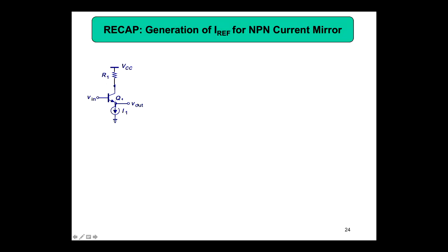It is an emitter follower, because here your input is to the base and the output is from the emitter. And then here you need an NMOS, because then only you can make a current source. And then we will be connecting a constant DC voltage, because this is a signal you are connecting. This voltage will set the current.